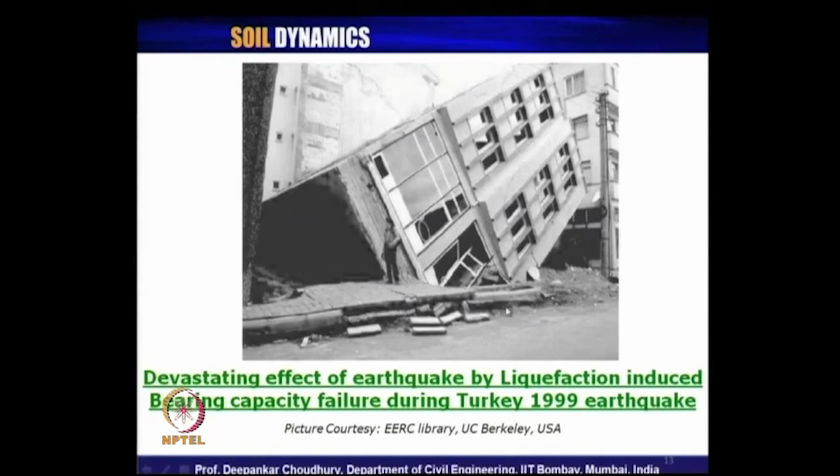The behavior of the soil under that kind of earthquake or dynamic loading was not considered properly, or it has been liquefied in this region. That is why, though the superstructure was constructed very nicely, because of the foundation failure the entire structure has toppled down like this, and it again shows the need to study the course on soil dynamics.